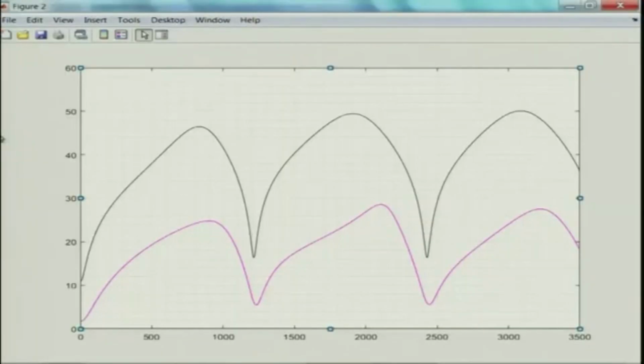If you play back your last lectures at your leisure time, you will see that we used a variety of different perforate impedance expressions, and we did not quite see much of a difference, even when the flow was about 0.15, 0.12 or something like that. We did not quite see much of a difference. But for cross flow configurations, it's quite important, because here you have a non-zero bias flow, and that will definitely add a lot of damping, a lot of attenuation.